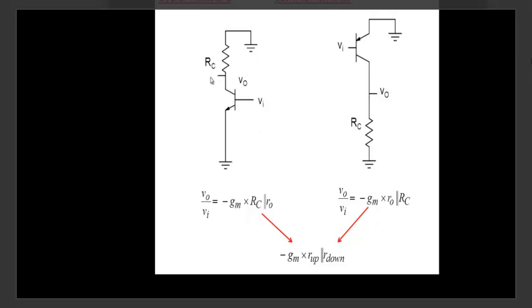And what is the Norton's resistance? When you look at any particular node, there may be a part of the circuit on the upper half, and a part of the circuit on the lower half. So that's what we are saying: whatever is the resistance of the upper half, whatever is the resistance of the lower half, take the parallel combination. So whenever you encounter a new situation and you have to find a gain or a voltage at a particular point, small signal gain, a simple method would be to build a Norton's equivalent.